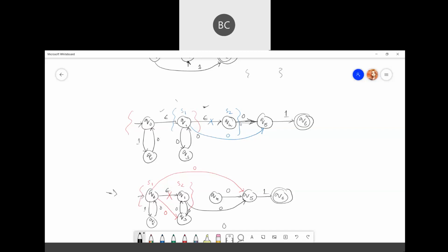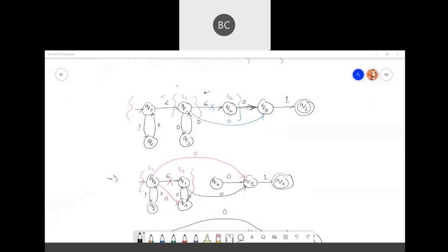Select the one pair where the next state will have some conditions with any inputs. Therefore, we have selected this part, state 1, state 2. This is the first pair we are considering. Then we are considering this second. The rest are just do it one by one. Is the process clear? Okay, very good.